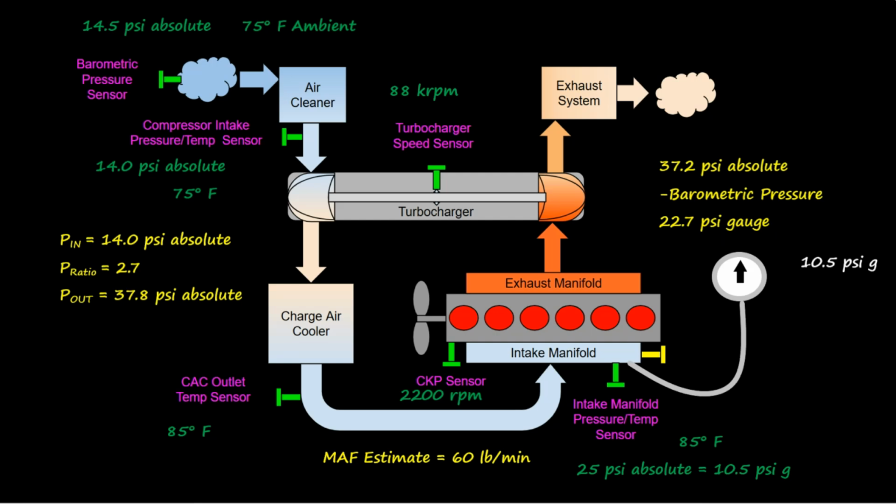So in this case, the physical pressure gauge and the MAP sensor both agree with each other. So that indicates our problem is not with the MAP sensor or anything there, probably in the intake manifold. In this case, we can probably say that our mass airflow estimate is probably correct. So we've got something else that's wrong. Well, the things that could be wrong is we could be measuring turbo speed incorrectly, but that sensor measurement system is pretty robust and not so prone to failure typically. So one of the more likely causes of this would be a boost leak.